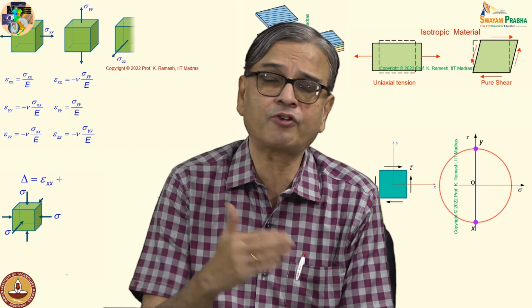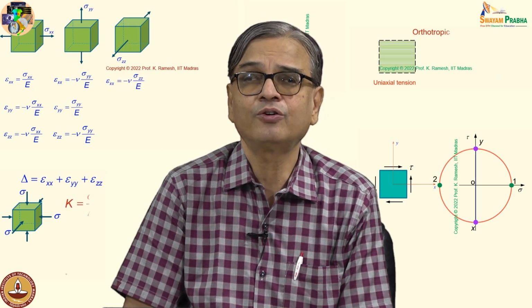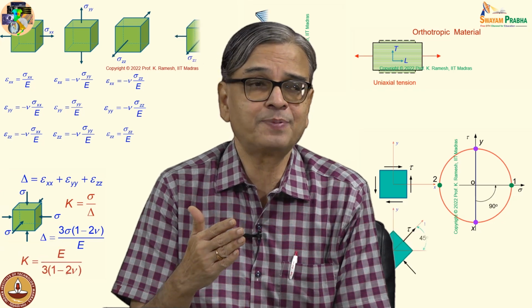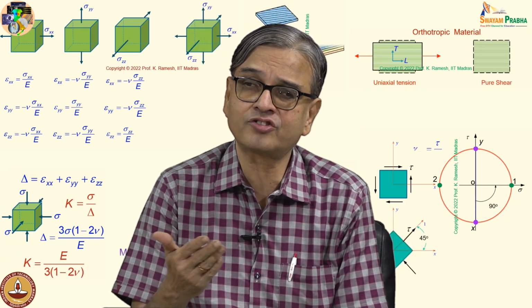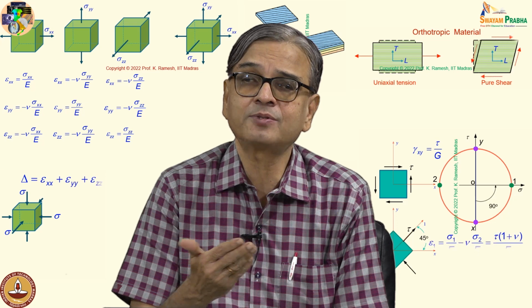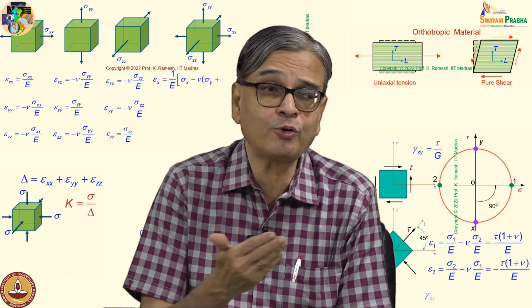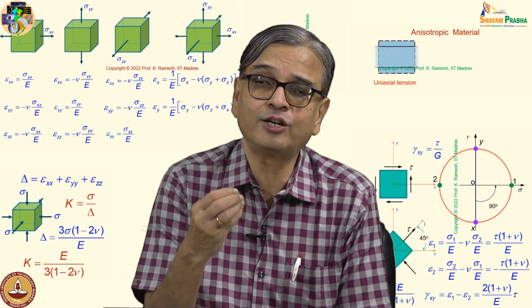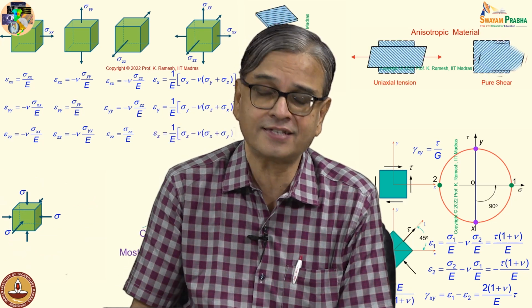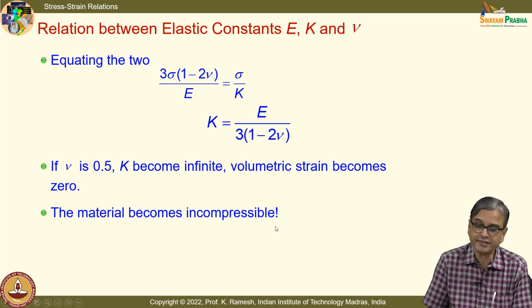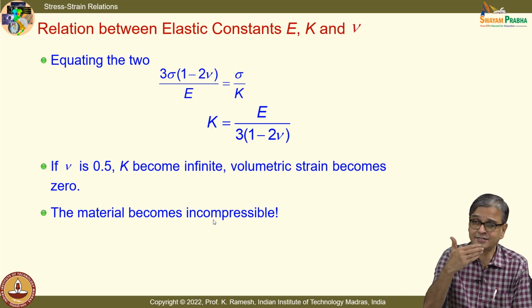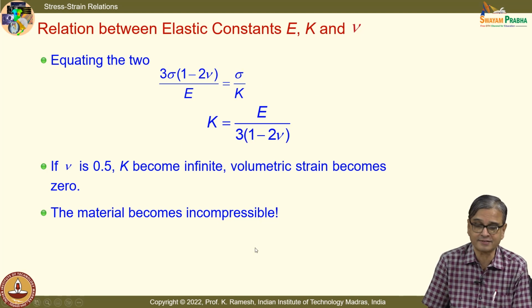Particularly in the development of plasticity, it's very mathematically highly demanding. One of the aspects we have also looked at when we discuss strain gauges, when the material becomes plastic, the Poisson ratio approaches 0.5. So, one of the idealizations they do in simple plasticity theories is that the volume remains constant. That is one of the conveniences in simplifying the material model that comes from a discussion like this.